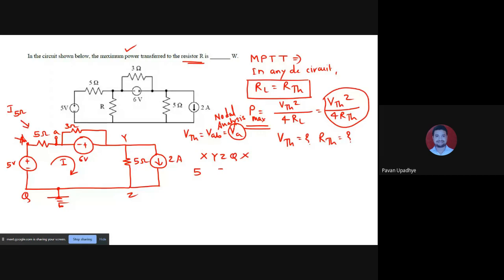That is 5 into I, and the current and I are moving in the same direction, so minus, and then plus 6 volt, because it is a rise in potential for the battery. You don't need to look at the parallel branch because we are looking at the outer loop, for the sake of understanding. And then minus 5 into I, and that's it, is equal to 0.